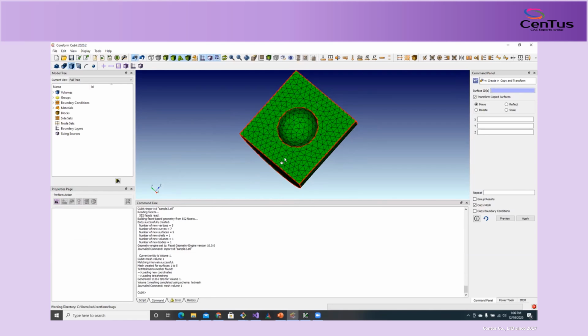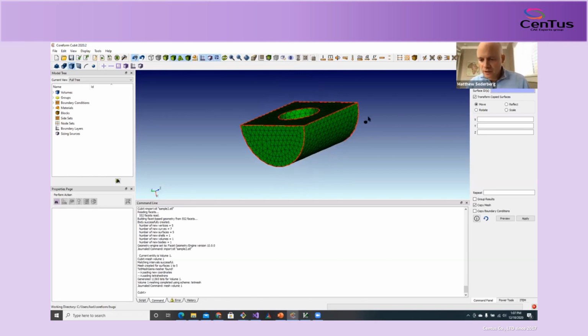And is that a typical STL workflow, Carl, or is this unusual? That's a little bit unusual, but it's not that unusual that STL just says put every surface out into a separate body. So you brought that in, because it reported those things as what we call sheet bodies, right? Yes, zero volume bodies. And we know we can't make a closed volume from those. We can't mesh it as a volume. You exported all the triangles as a volume, you read it back in, and then we are smart enough to make a volume out of that, right? Exactly. Yeah, okay, cool.